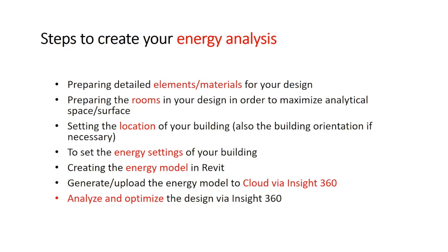Analytical properties are basically the thermal properties, for instance, the R value as well as the U value of that particular material. So it is important that you set this in your design before you send your model to Insight 360 for further analysis. Secondly, it is also important that you set the rooms in the design as well, because for energy analysis in Insight, they require you to determine the space as well as area and the volume to be computed in that model.